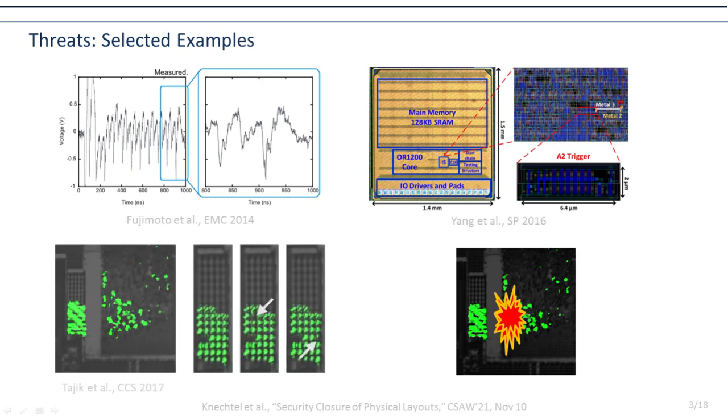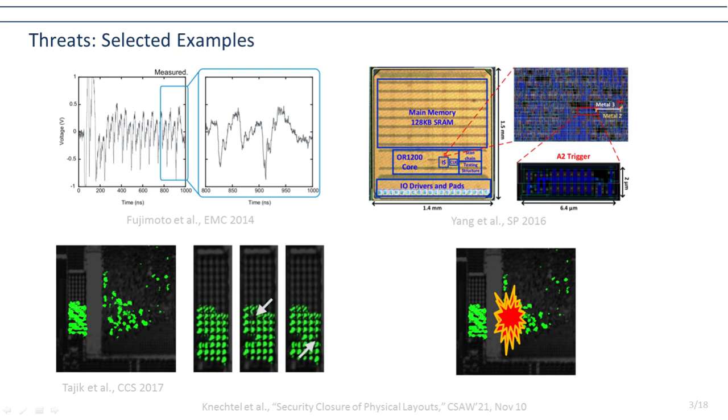Moving on to the lower left corner, what we see here is a top view and a cartoon representation of what is called electro-optical probing. This is basically a failure analysis technique which helps an adversary to infer the charges in the logic as well as in the memory cells. With this approach, we can basically understand the bit 0 or 1, as in literally reading out the data at runtime on the hardware. And this is quite powerful as well, as you can imagine.